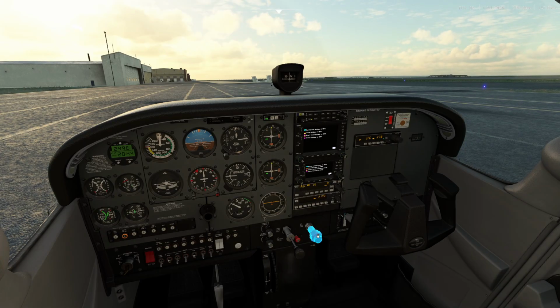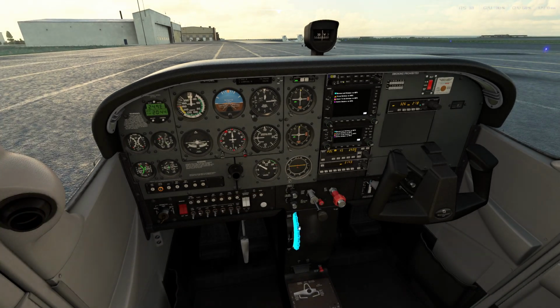And the idea here, it shouldn't actually be manipulating the trim by itself here on the ground. That's kind of a little quirk, I guess, of the default aircraft. But whatever. Flight control, so move in all directions. So left, right. Now you didn't actually see the control column move left to right on screen. I think it's just another quirk of the sim, but nonetheless, what we're checking for is to make sure that we can physically overpower the autopilot itself. So we'll go ahead, full in, full out, and then next step is going to be to disengage the autopilot, and we're going to hear the disconnect tone.